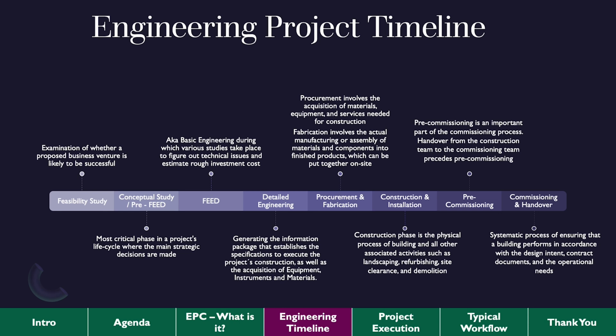So the critical part here is the datasheet specification that has already been done in the basic engineering part, which basically supplies the process data, followed by a mechanical engineer adding that piece of the puzzle on his end. Because when you are doing a heat exchanger, there is the thermal design that the chemical engineer would do, for example, and then you have the mechanical design that the mechanical engineer would finish. And once those are there, the procurement only has the freedom to pick the type of material that has been specified in those data sheets.